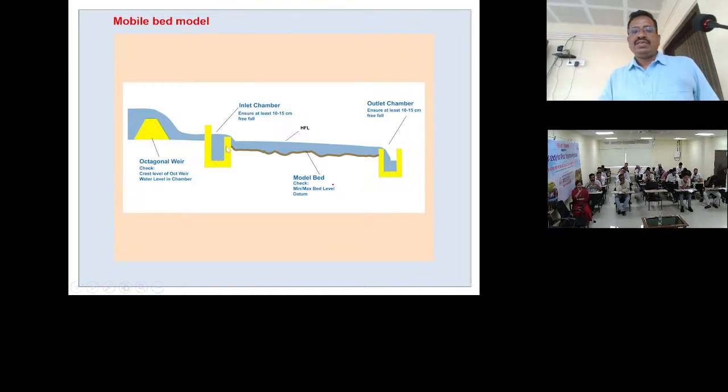So we release 7,000 from here, and meanwhile there are three gauging stations on the Yamuna river: Wazirabad barrage, Indraprastha barrage and Okhla barrage. The water levels at those places are known for particular discharges. So if we are releasing 7,000 here, we have to check whether the 204 level at Wazirabad is matching or not. Again here 202 and 201, like that.